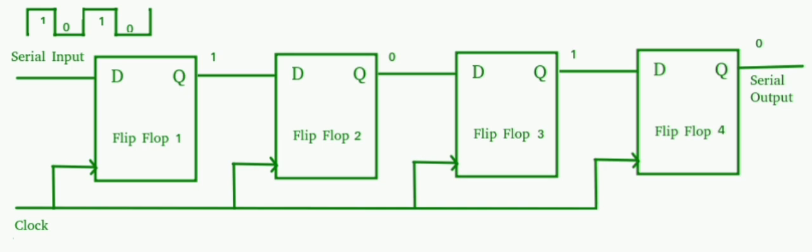Decoding is very easy in ring counter because there is no need of extra circuit. Ring counter is a non-self starting counter. In a 4-bit ring counter, used states equal 4, unused states equal 2 power 4 minus 4, equal to 12. In a ring counter, if clock frequency is f, the flip-flop output frequency is f by n, where n equals number of states equals modulus of the counter.